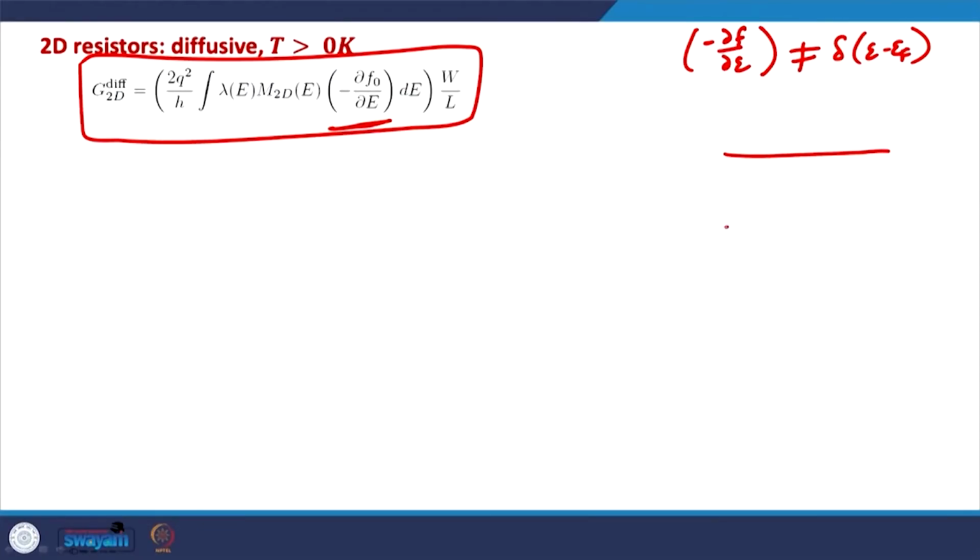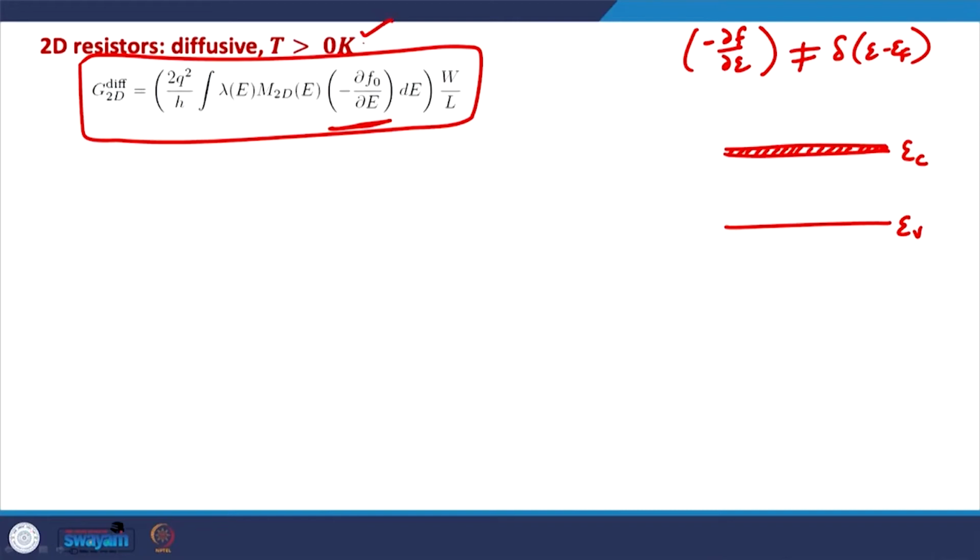So, if we have the valence band and the conduction band, most of the conduction electrons are quite close to the bottom of the conduction band, and in this case even the Fermi-Dirac function can be approximated by the exponential function. Things are more difficult when we have to deal with degenerate semiconductors or extremely highly doped semiconductors.